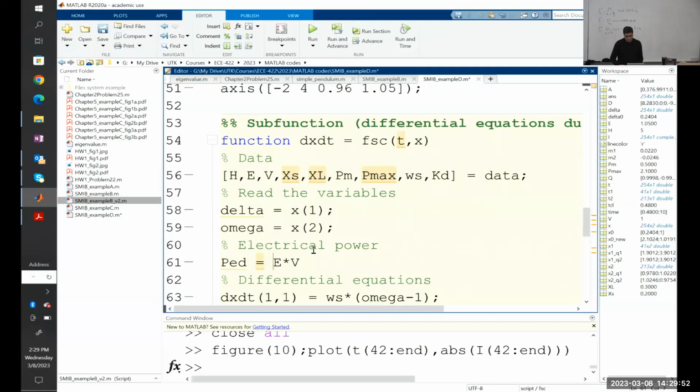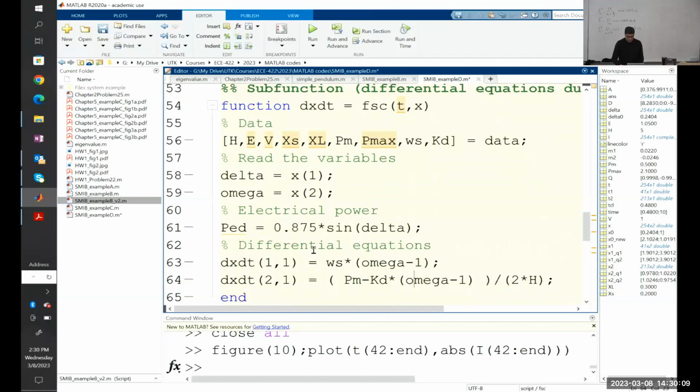We can put the equation there. What about if we put directly the value we obtained, 0.75? But in a general system, probably it would be better that we calculate there how much is XAB. So that's electrical power during the short circuit. And that's what we're going to put right there. So that's the new equation during the short circuit.